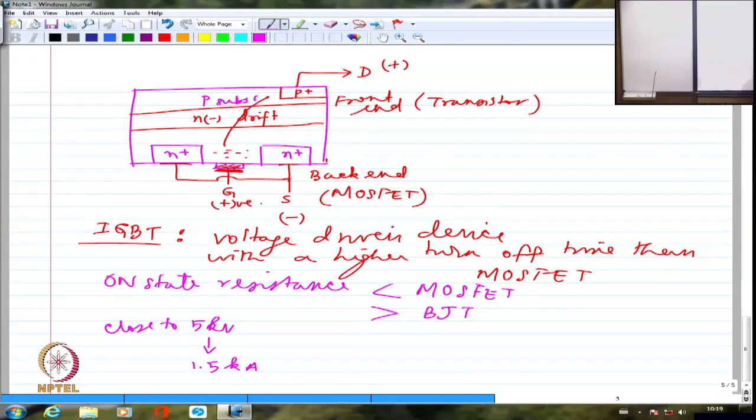But if we try to come for lower values of voltage, that is, let us say 2 or 2.5 kilovolts, we can easily get 3 kiloamperes and so on. So, if you lower the voltage, you can go for a higher current, because heat sink design is a big problem generally. So, we have at least of the order of 6 megawatt handling capacity quite easily in many of the IGBTs. Single-handedly they can handle 6 megawatt, and as the research progresses, in all probability we may get higher and higher rating possible. Okay.